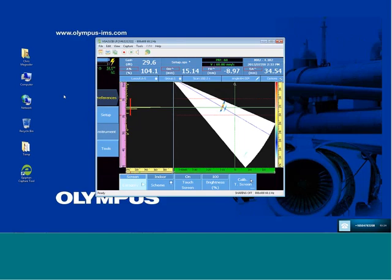So I'm going to position my reference and measure cursor over the TOFD area and identify the lateral wave that I see here and enter the wizard normally. Calibration, lateral wave, synchronization. Okay, I verify that my cursors are in the good position.